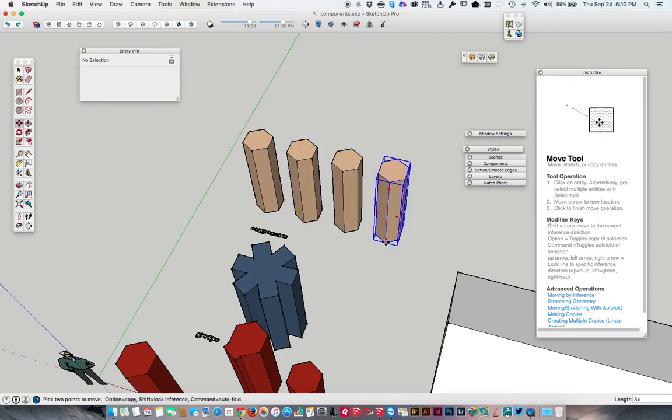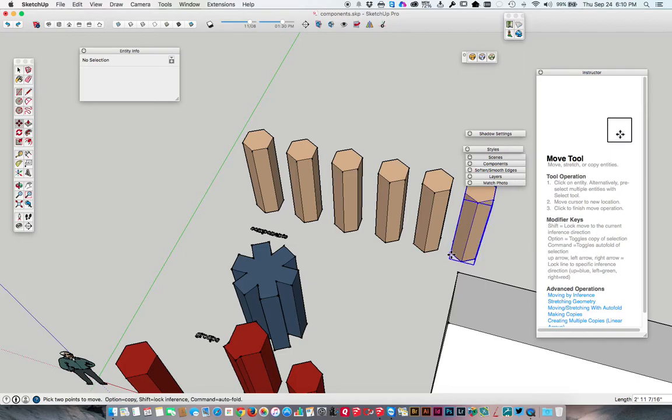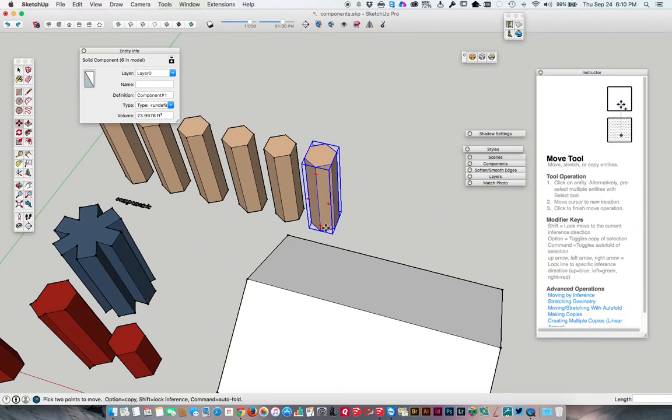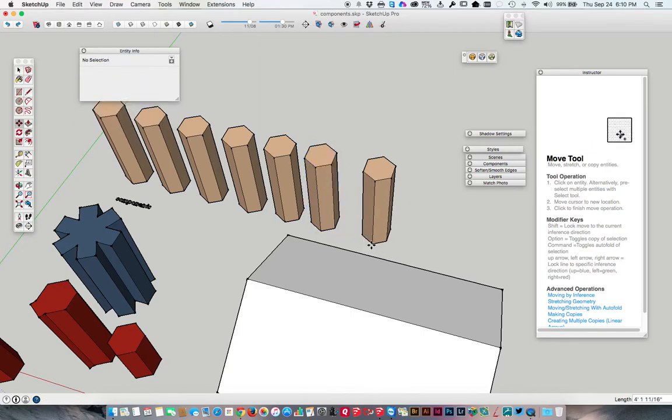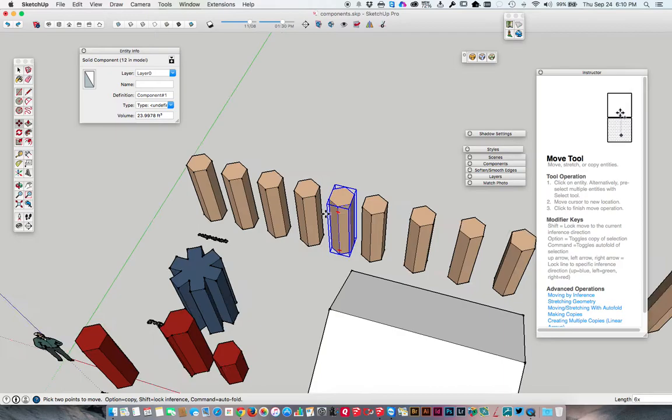But basically now that's a quick way of making multiple copies. I don't have to go here and make 1 copy and then 2 copies, and oh, I didn't get the spacing right. All I have to do is just say copy it from here to here and hit however number of copies you want. Let's do 6 copies, and then hit 6x for 6 times, and then hit enter, and it creates 5 more copies using the same spacing. Right, so that's a little trick.